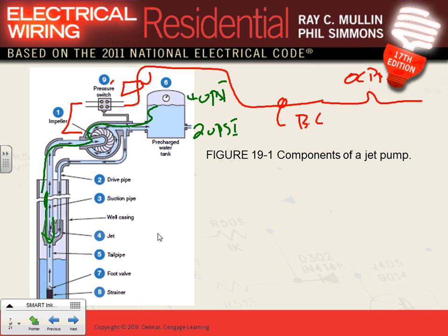So it keeps charging the tank until you hit a pressure of 40 psi. You fill it, basically. Then that pressure switch will open because it's pressure activated. It's looking at the pressure here. When it reaches this 40 psi or so, it will open and de-energize the circuit. Then you keep taking all the water until you hit another pressure, which is 20 psi. Then it closes again and does the cycle itself, right?